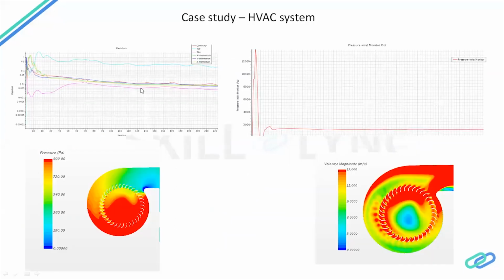Once the physics is set up, we can study the monitors and what the pressure is. This is the pressure variation. This is the velocity variation across the flow. Now you can see we have a dead zone. The blue is like 0 Pascal, and we don't have any pressure. I mean, you can say this zone is of no use because of the sharp edge. If you see the velocity here, because of the sharp edge, the velocity is separating. So we have a recirculation zone, and because of the recirculation zone, we have a dead zone here. From this type of inference we can try to change the shape. That is called optimization.